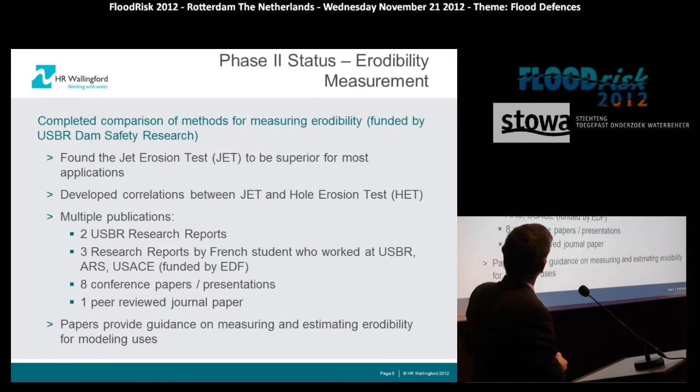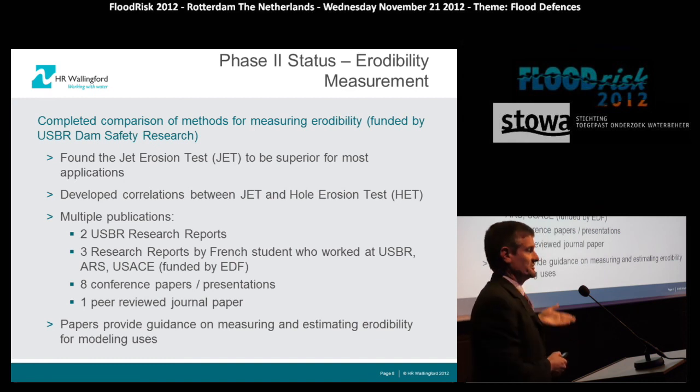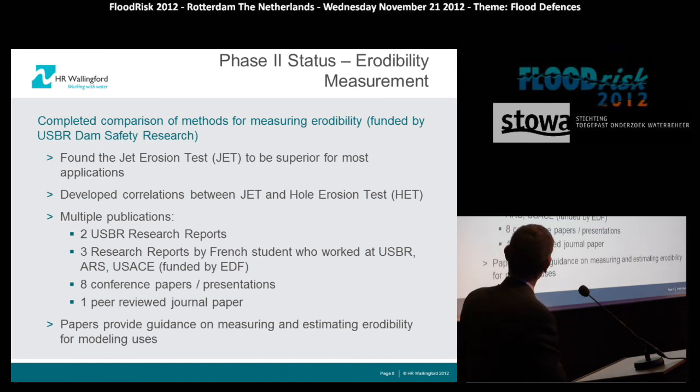So I'll come straight on to it. The soil erodibility work was really comparing the jet erosion test with the hole erosion test. Jet erosion test developed in the States at Stillwater, jetting water at a piece of soil. Hole erosion test, squirting water through a hole to test the erodibility of soil.